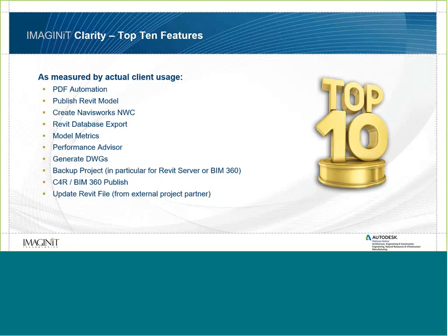Clarity can do that. You can set up a task that'll run every Friday at 10 p.m., every Saturday morning at 2 a.m., midnight, whatever time you need it to be. You can take your Revit file. As it goes through that Revit file, if you need to, purge it, delete views, delete sheets, delete views not on sheets, compact the file, whatever. You do some basic cleanup of that file and then send it off to your design partners. And do that every Friday, so you don't have to worry about it. It's part of getting that Friday back in your life.